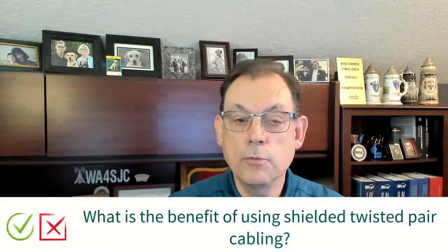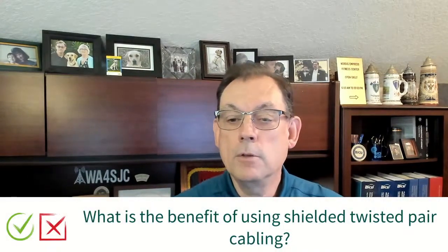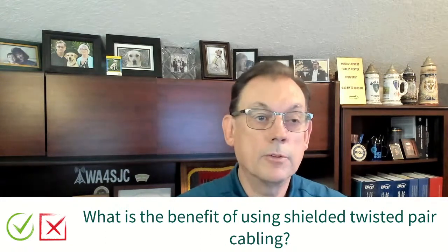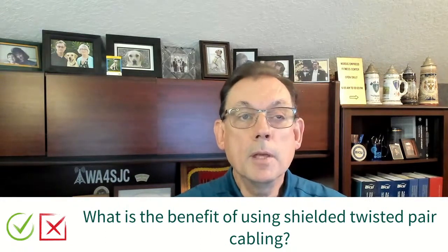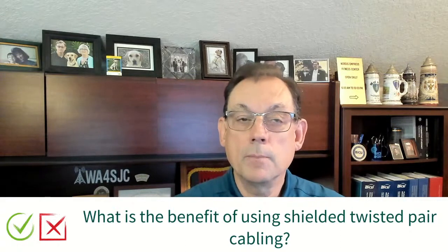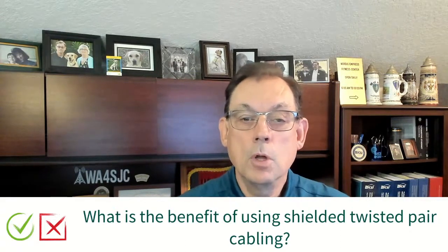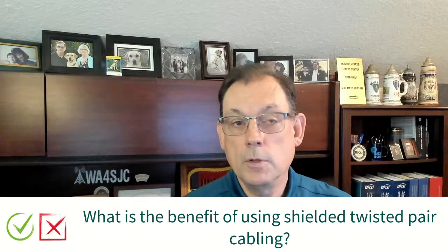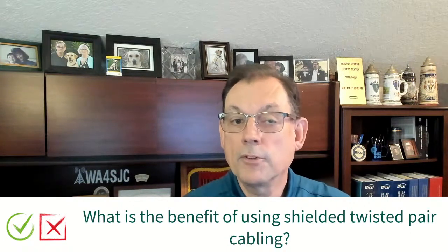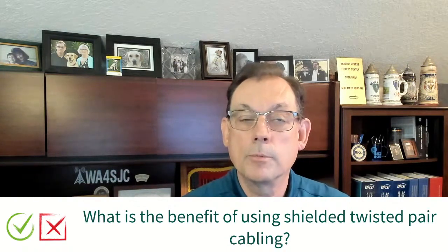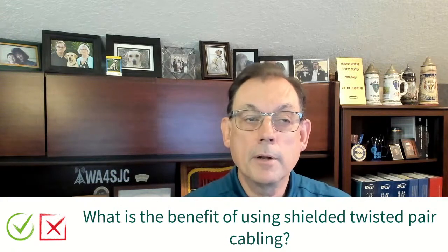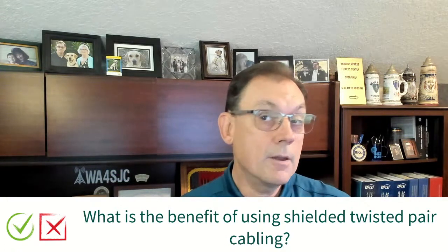We've had some questions come in ahead of time, so question number 2, Jacqueline, if you could bring that up for me. What is the benefit of using shielded twisted pair cabling? We'll start with that one. The big benefit is that it helps to keep noise out, so noise doesn't ingress into the cabling and cause problems with your data transmission. But it also helps to keep noise from getting out of the cable.